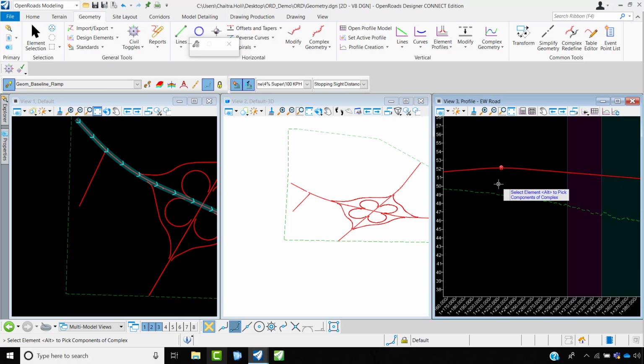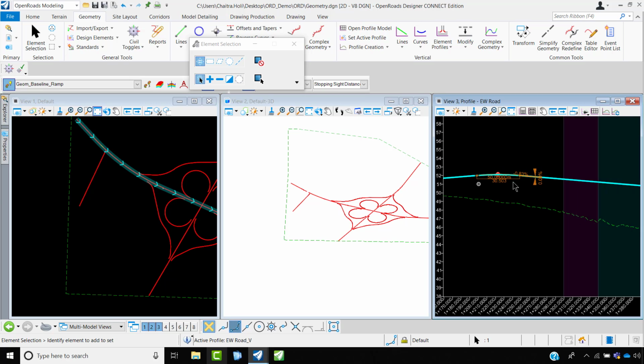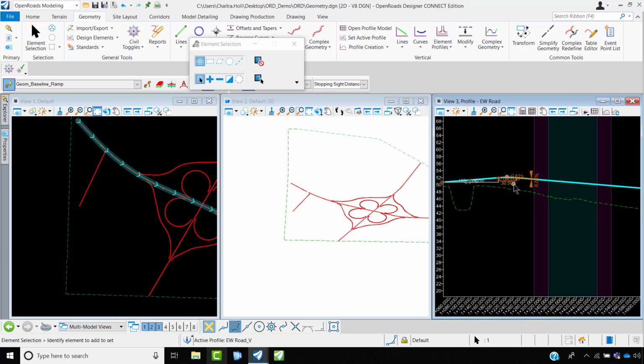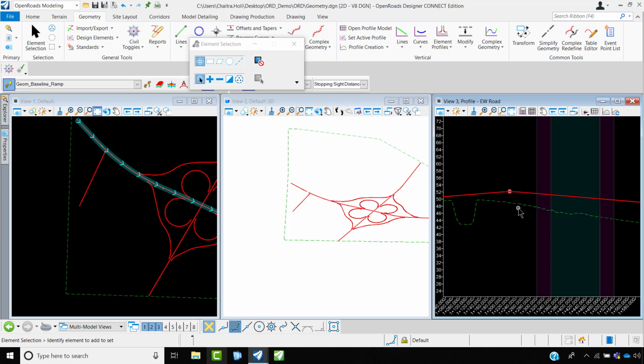As soon as you set the design standards even for your profile, you could see that errors also being displayed over here. It says that crest is less, actual value should be 52, what we have provided is 30.44. You could either go and make any changes or move ahead with your design. Right now I'm not going to show any changes with the vertical profile, so I'll move ahead with this.